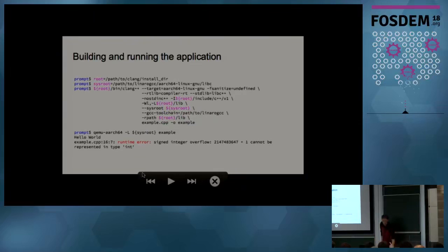A quick important comment about that is that you should really use both the GCC toolchain and sysroot, because GCC has build time configuration, and the sysroot can be laid out in slightly different ways depending on whether it's Debian, Ubuntu, CentOS, or even the model. So you should use both. Just at the bottom there, that's using QEMU.